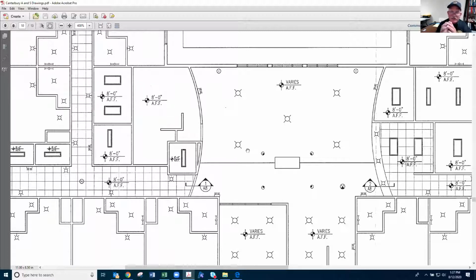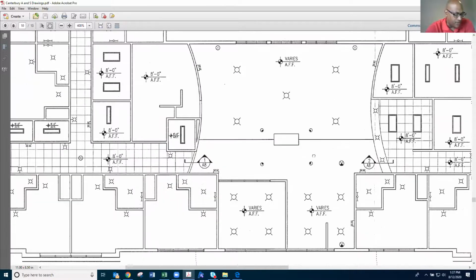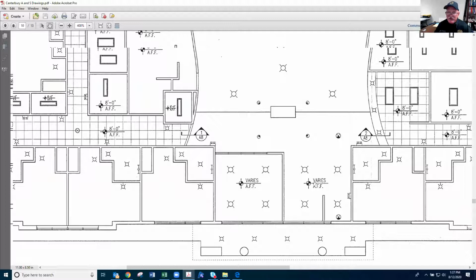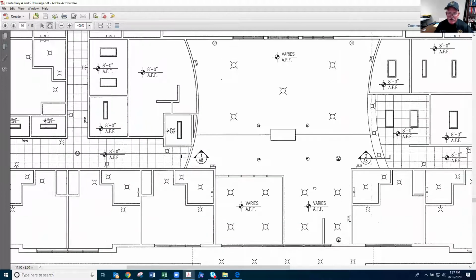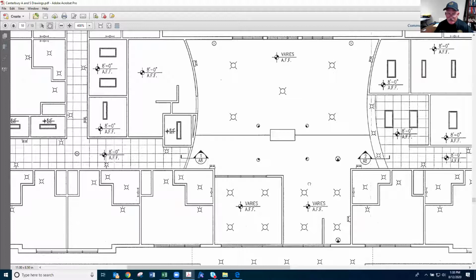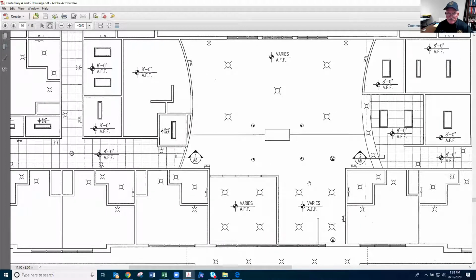What do you really not see in that cafeteria? I don't see any doors in this cafeteria, do you? That's what I was wondering, where the doors are and how they swing. Yeah, there's no doors in this cafeteria that I can see. If you guys look back on the one we looked at earlier, are there any doors there? And if it seats more than 50 people, they're required to have 2 doors, isn't it?